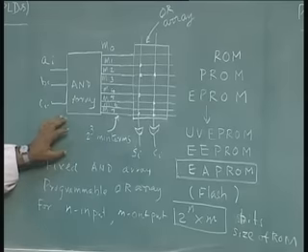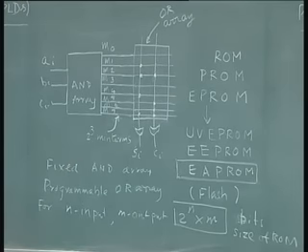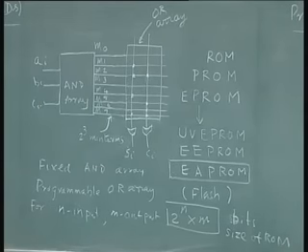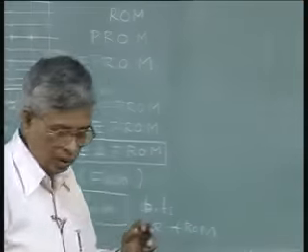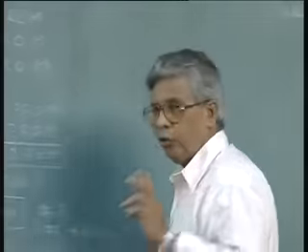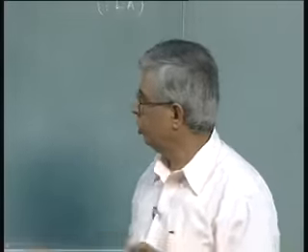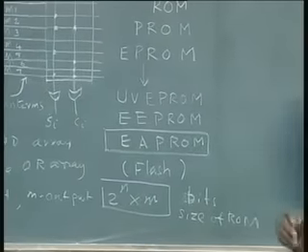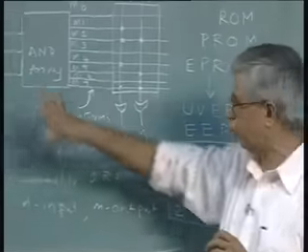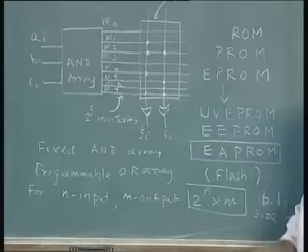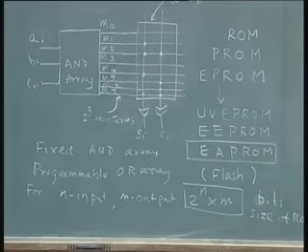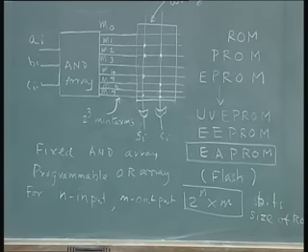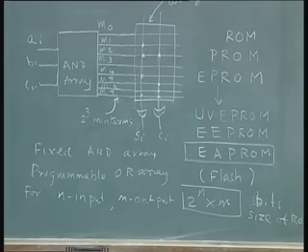So that is why I called it hardwired truth table. But in the programmable logic array case, I will use a few select product terms in order to generate the required output. That means I do not have to have a whole set of AND gates 2 power n, I will have a fewer number of AND gates and generate a bunch of product terms which will be used in the implementation of the final output.